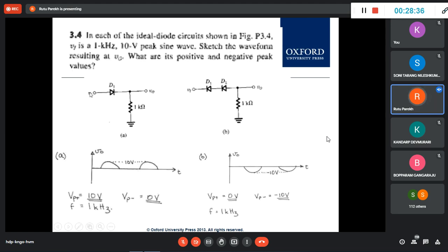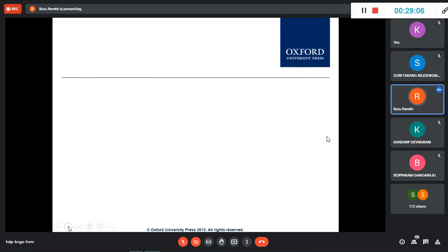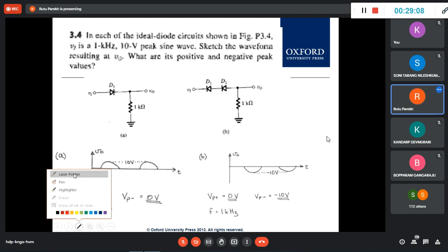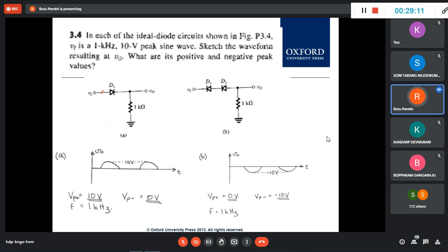Right? This is a signal, this is a sine wave, but it is a big wave. This is really big. It is always conducting for the positive half, and that little drop is no matter. So you take it as 100 only. So this is operating only. Little drop is nothing. With 200 volt, what is a 0.7 drop? Nothing. So this output is shorted. When we are talking of high volt and it is conducting, it is shorted.